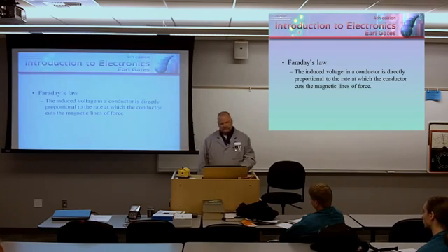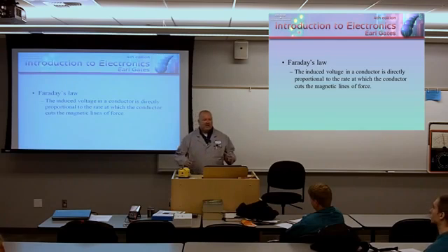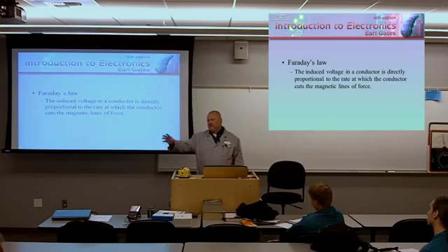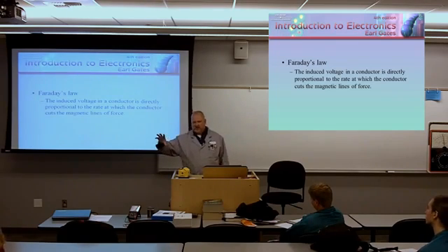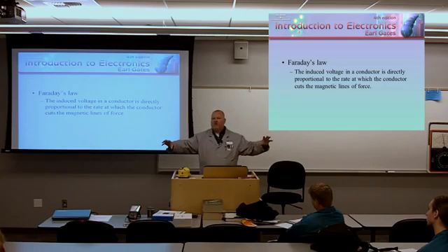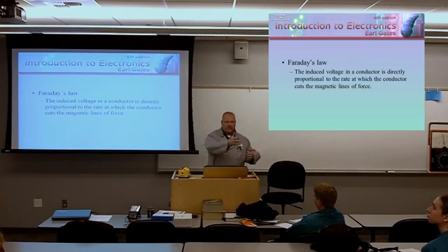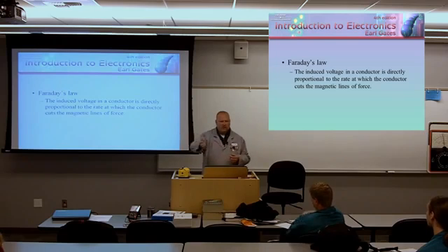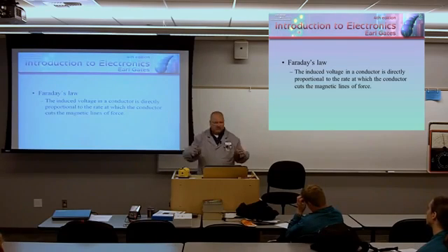Faraday's law. The induced voltage in a conductor is directly proportional to the rate at which the conductor cuts the magnetic lines of force. Okay? I'm going to make this real simple for you to understand. Envision up here that I have a big north pole, a big magnet sitting here, and here I have a big south pole. You all agree that I've got lines of flux going from the north pole to the south pole, the straightest line, the shortest distance, right? So in between here, I'm going to have a strong magnetic field. Do you agree with that?